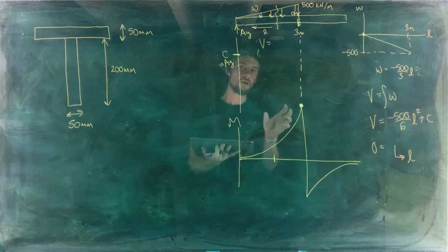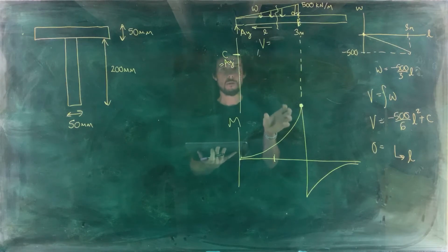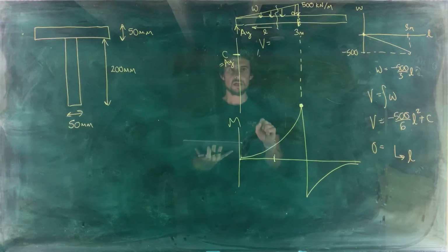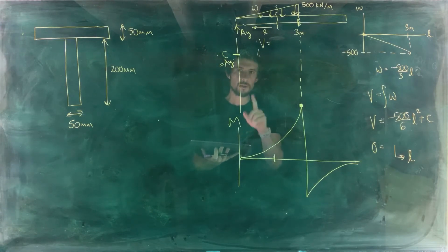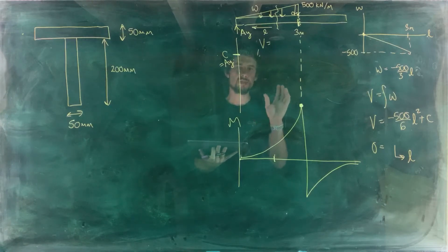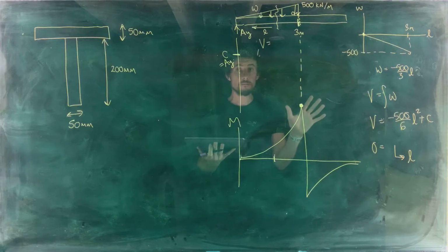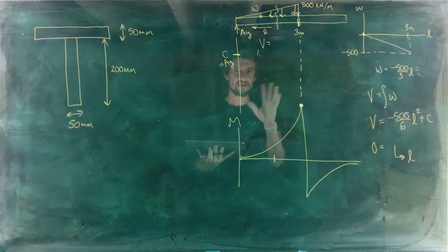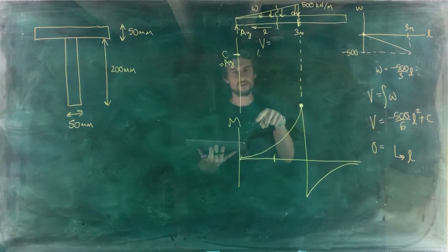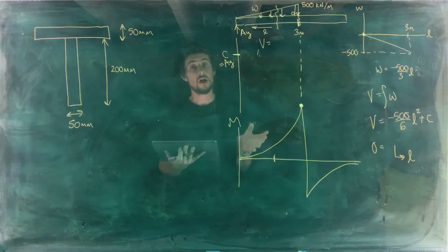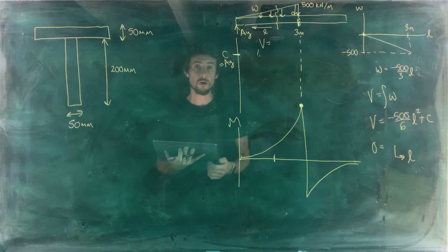And depending on what your connector looks like, it might be helpful to do an exploded view of the assembly too. For instance, if you have some pins going through, depending on whether you're setting materials for the different elements to visually separate them by color. Sometimes in assembly drawings, components can get hidden if they're all the same color and you've got a pin that fits perfectly into a hole. Then the outline of it maybe is not so apparent. So doing an exploded view would help in that case.